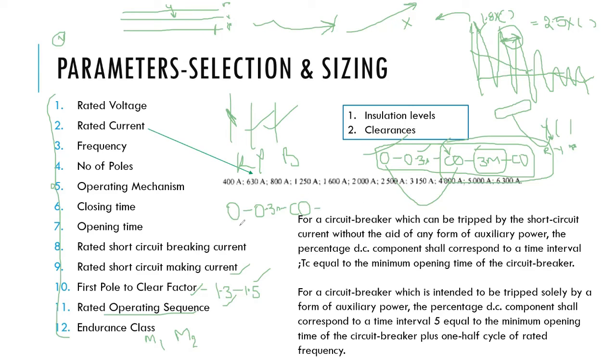Now let's see, the breaker opened twice. The breaker opening twice means the moving contact is moving away from the fixed contact. This is a fixed contact, this is a moving contact, and the moving contact is moving away from it. So there is an arc formation. This arc is quenched by the SF6 gas surrounding it. How many times? Two times. If it is done two times, then the SF6 gas present here gets ionized.